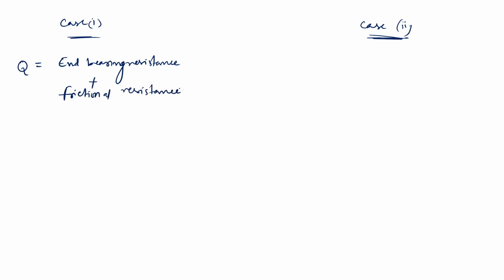The capacity is imparted from these two, then that can be written as area of the bearing multiplied by c Nc plus surface area multiplied by alpha adhesion factor into undrained cohesion. This is for only clays. So average cohesion over the depth multiplied by alpha adhesion factor multiplied by surface area. So this is the formula.